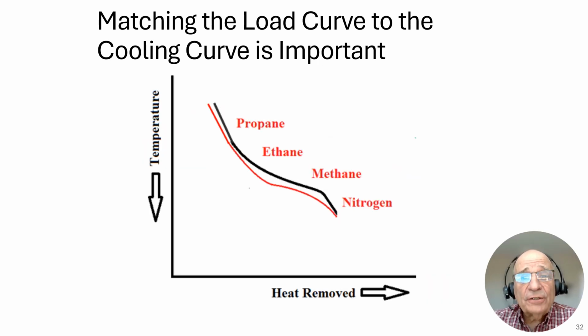The load refrigeration curve would look something like this. Now, the shape of this curve is really dependent upon the composition of your feed gas, and the shape of this curve is really dependent upon the composition of your MR.